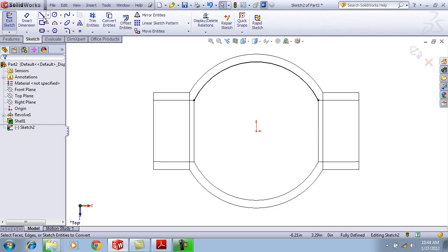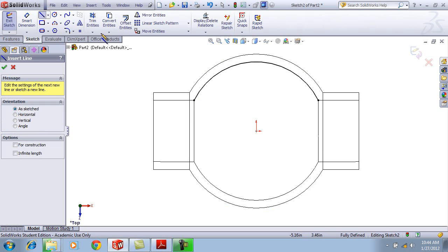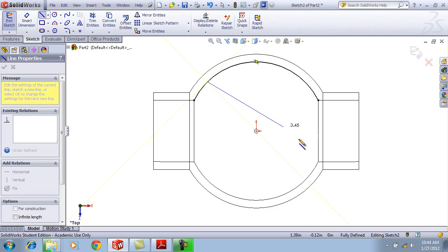The next thing you can do is take the line tool, so select line, glide up here onto this curve that we just converted. Right about here in the upper left, somewhere, click, and drag this across. Drag it pretty far, actually drag it out beyond the boundaries of your actual geometry there.